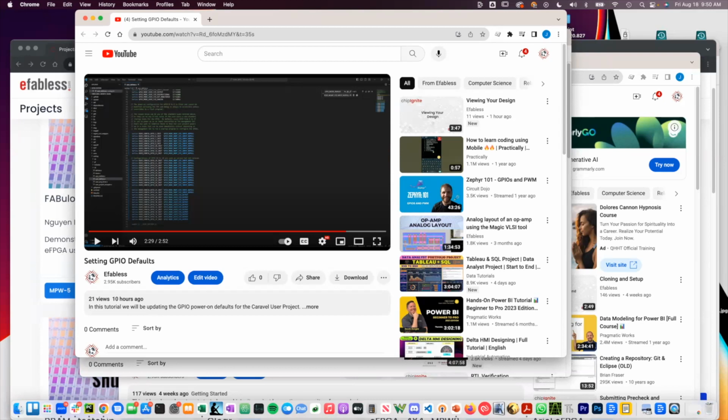So there are ways of getting a large capacity RAM interface to the chip if you're looking to do something that involves moving a lot of data through the chip to, for example, show that an accelerator works. The simplest of those is to use a serial connection between Caravel and another microcontroller that has a large RAM interface.